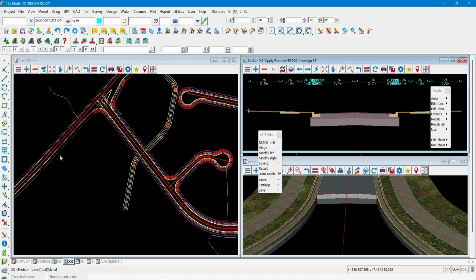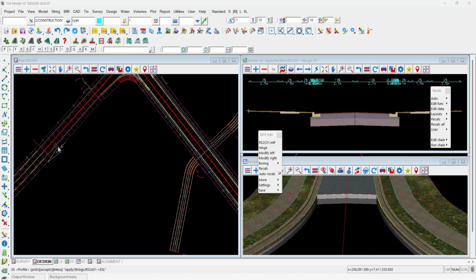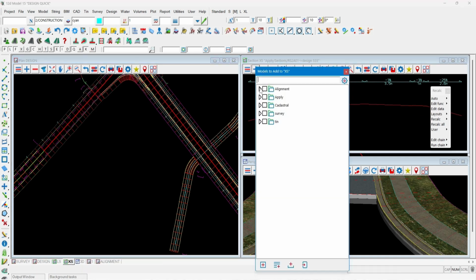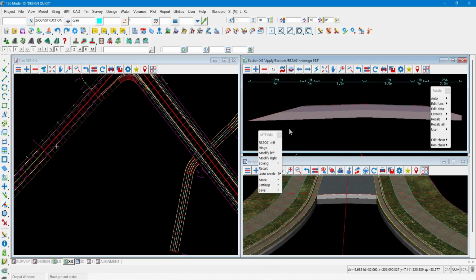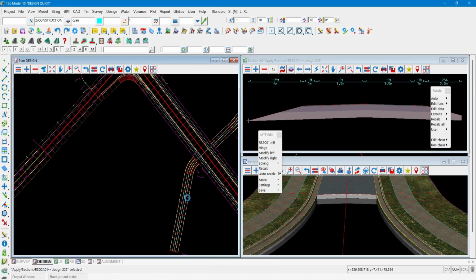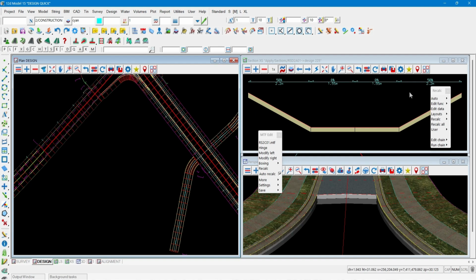And if we go and profile one of our rural road cross sections, you'll see that that pavement, when I turn on the tri-meshes, has a rural type pavement already applied in the design quick start. And our trapezoidal channel, if I profile one of those cross sections, you'll see that that's a trapezoidal shape with some default dimensions, and it's got pavements assigned to those as well. Okay, so the design quick start in that pavement region has some pavements already created for us.